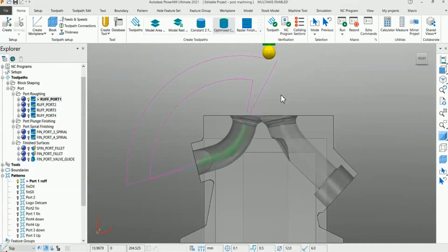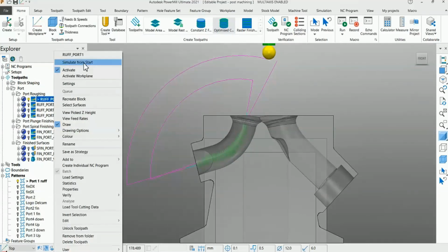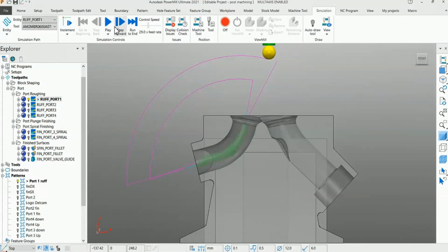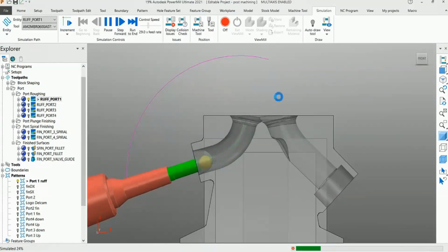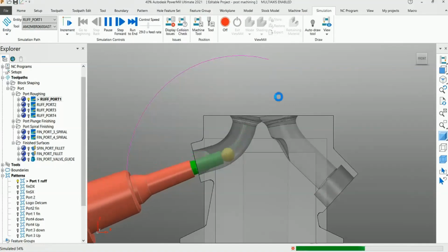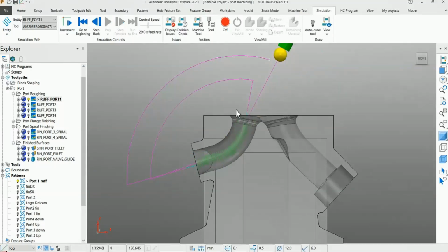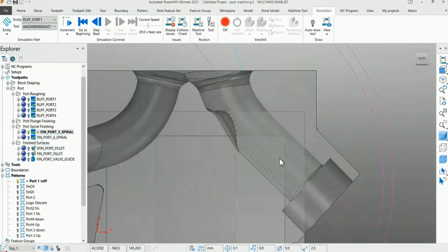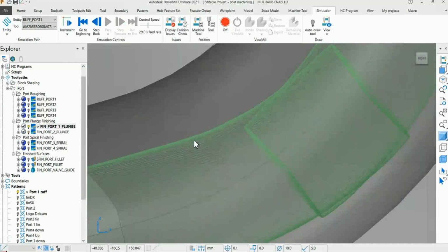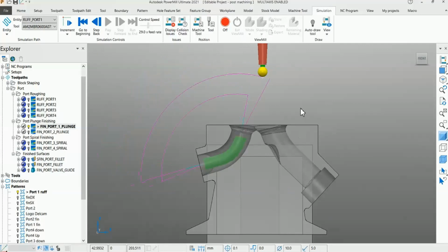If you go for 3+2 machining, the programmer has to create multiple work planes and multiple toolpaths to complete the same profile. If you look at the simulation of this toolpath, it starts safely from the start. Then it completely avoids all the collisions between the holder and the model. In a similar fashion, there are also dedicated finishing toolpath strategies, as a spiral motion or as a plunge motion. By using this dedicated strategy, 5-axis continuous roughing has more advantages over 3+2 roughing.